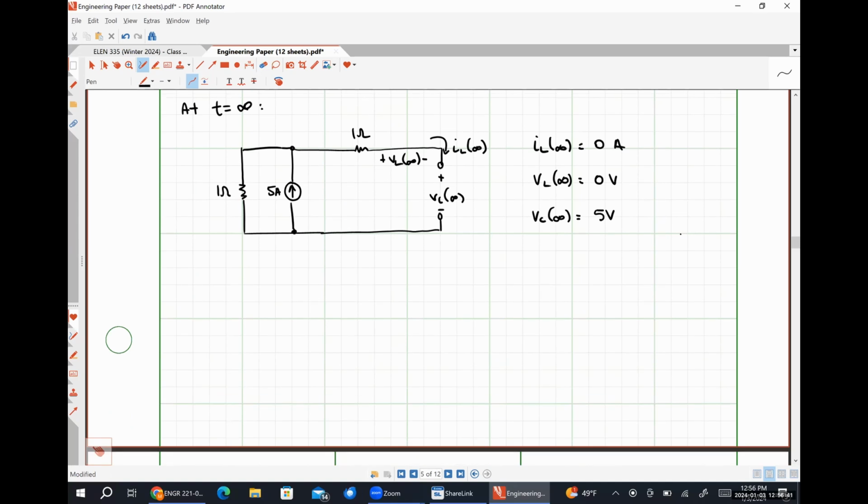So because this is a critically damped circuit, I can say that I of t is of the form, oh gosh, let's see, A1 t e to the negative alpha t plus A2 e to the negative alpha t plus I at infinity. Right, I don't have the table in front of me, so if I made a mistake, please tell me, but I believe I remember it correctly.